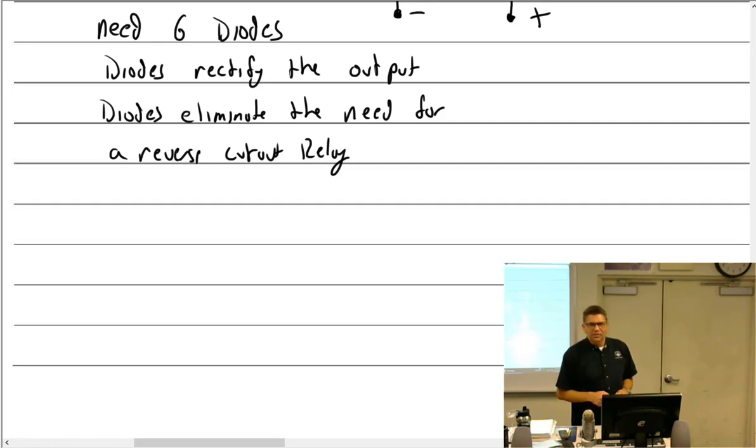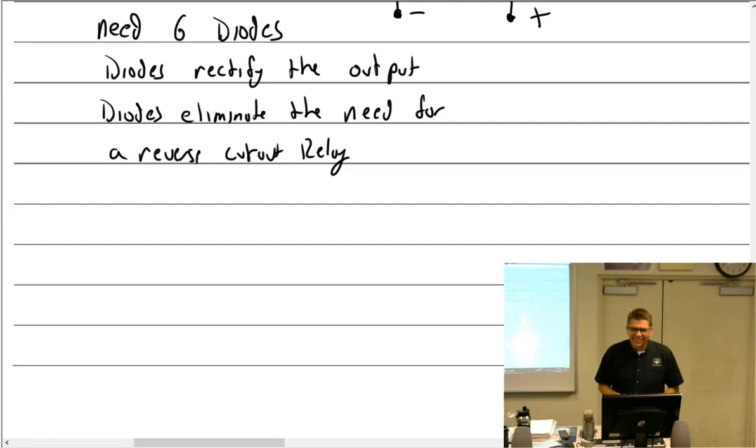So how do I know when I turn on the motor that drives the generator or the alternator that it's working? Voltage should go up above battery voltage. Same thing in an aircraft. If the voltage remains about 12, 12.6, and you're like, I don't know if the generator or alternator is working, guess what? It's not. So it's got to go above the battery voltage. That's why I ask, how do I know if this is going to work? The voltage meter is going to go above the battery voltage, and then it's going to work.